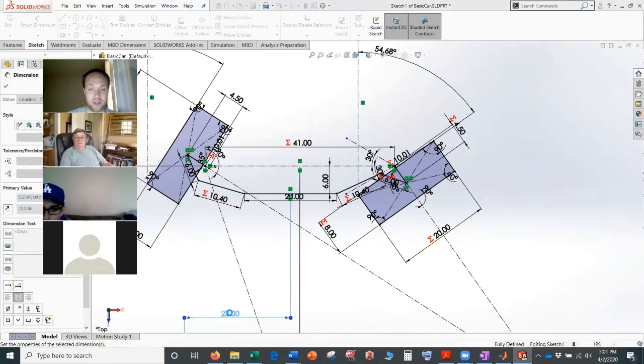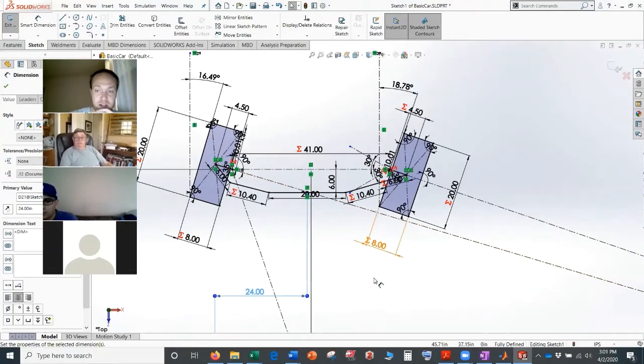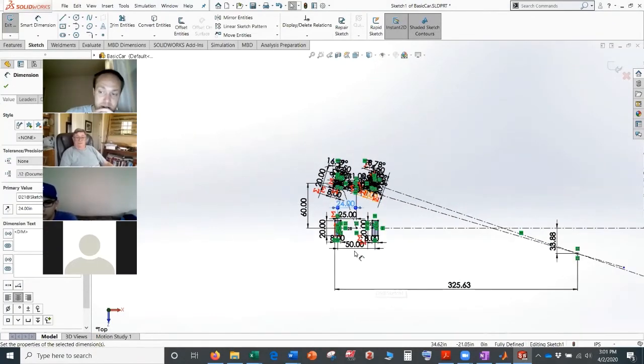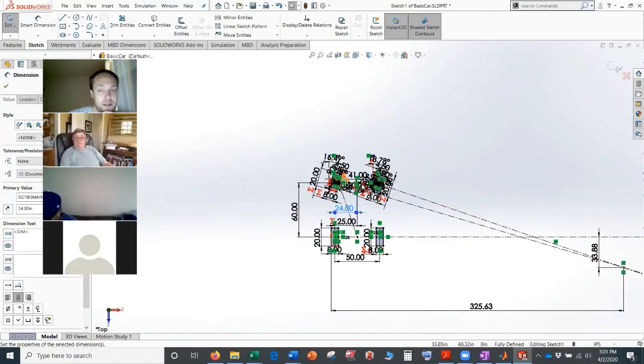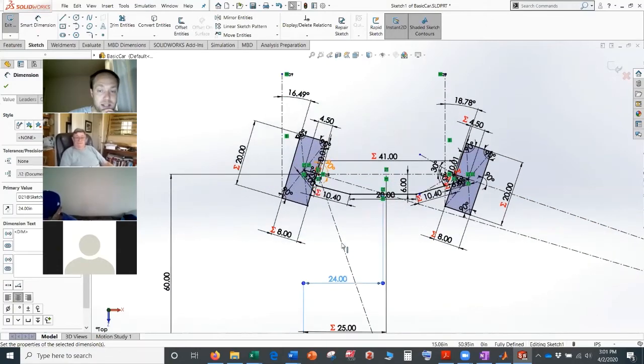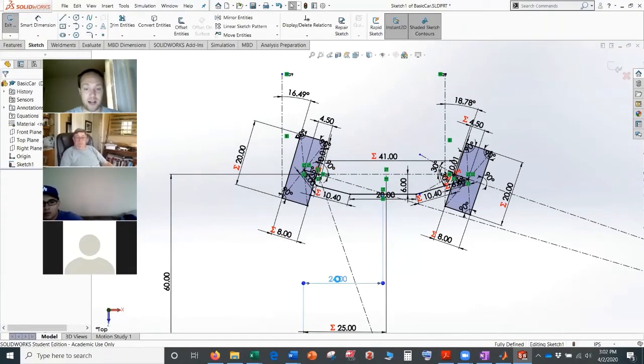So let's go back to the 24 where it was about straight. In this case, our turning radius is about 325. That's where they kind of all meet, roughly. And you'll notice we're kind of Ackermann deficient. Our turning radius for our 2 front wheels is meeting behind where our back 2 wheels will meet at, right? So let's try and get perfect Ackermann.